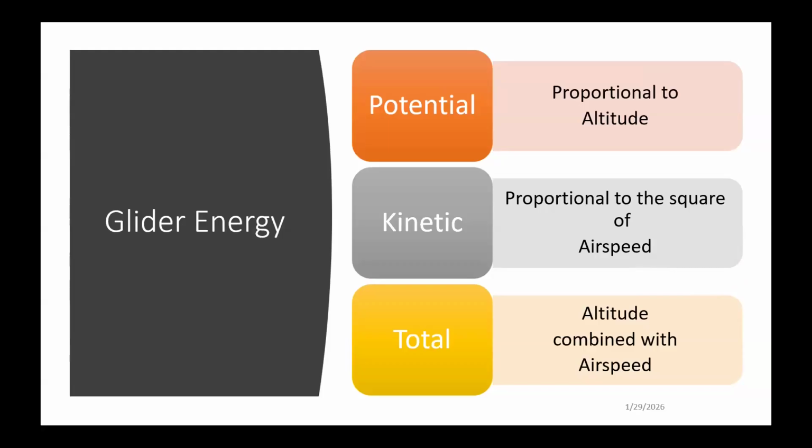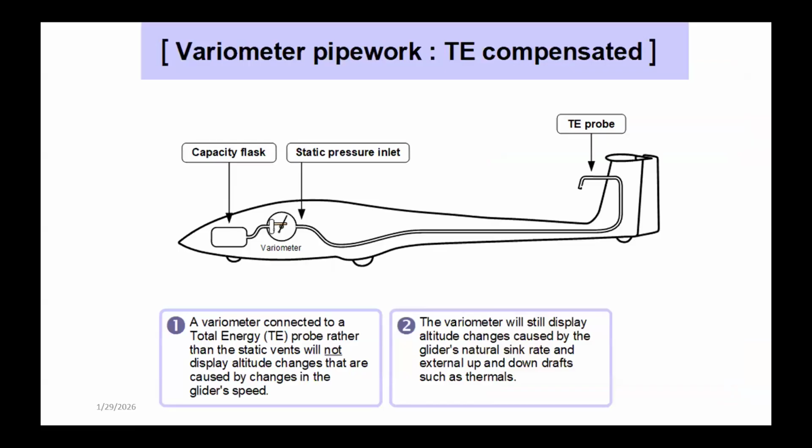The Vario is going to show a rate of change for altitude. You pull up and lift. So we're interested in the rate of change, the altitude gain while we're slowing. We're interested in seeing the change due to the atmosphere, the gain because of the lift. Okay. So there needs to be some way to factor airspeed into the Vario display to get rid of this thing of this energy change was because we changed airspeed. We've got to come up with a way to get that component out of the